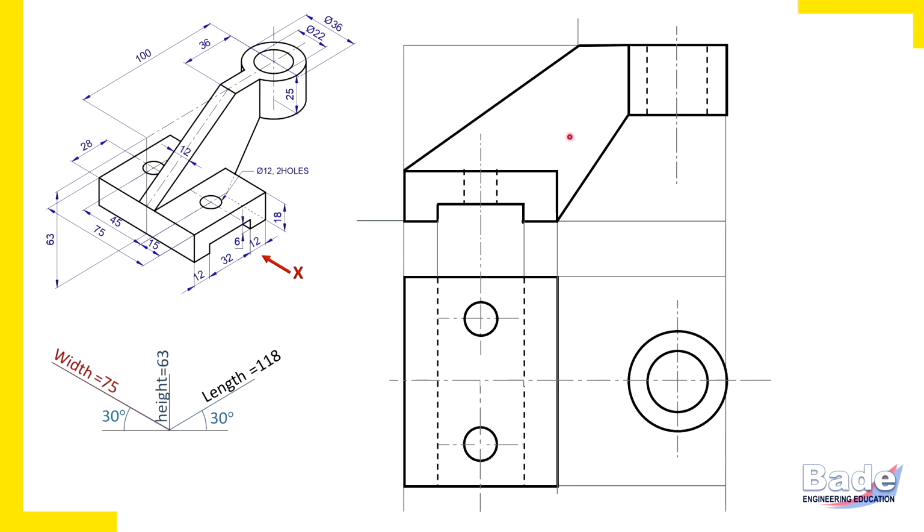Now draw end projectors of this plate. Watch this plate in the front view. Extreme right of the plate and extreme left of the plate. From these two extreme points, corners of the plate, we should draw projectors. These are called end projectors.